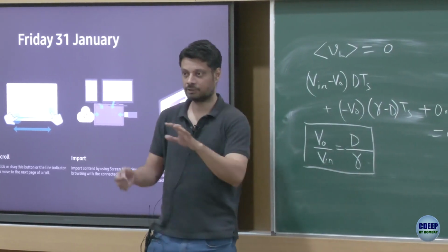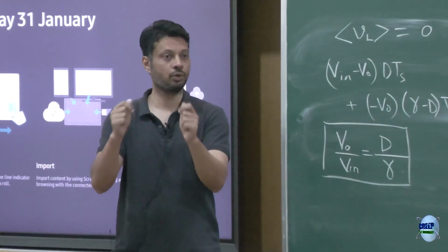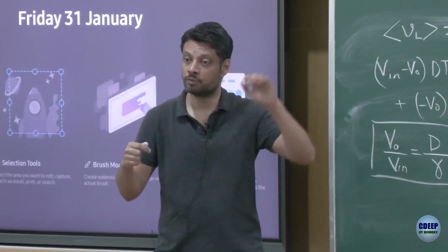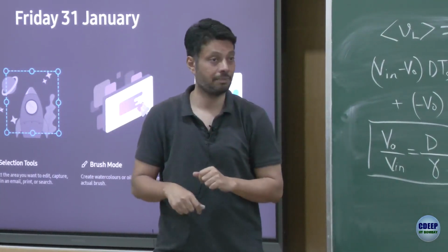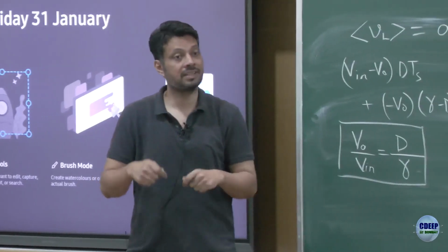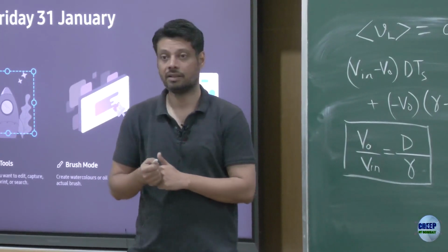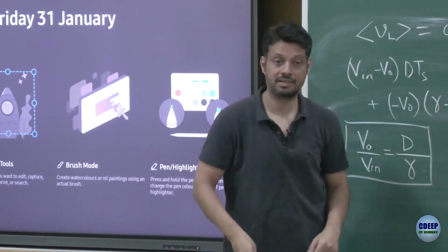Now assume that a converter was operating, and I have slowly started increasing the load resistance. I increased it a little bit, I moved from the earlier case 1 to case 2, and the output voltage remained the same. But now I further increase the load resistance, that means reduce the load current. Then I move from 2 to 3, this is the 3 waveform.